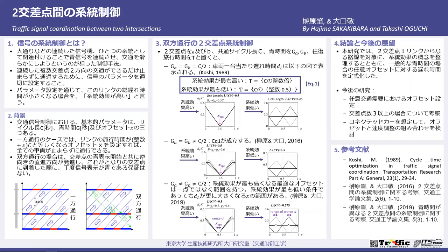The one-way road signal coordination is simple. If the vehicle meets the green light at the upstream, the onset of the adjacent downstream intersection is shifted by the travel time. The vehicle can pass without any stop. However, the two-way road coordination is much more complicated. The study can provide how the delay can be minimized by adjusting the offset between two successive intersections with given travel speed, distance between the two intersections, common cycle time, and the green splits.